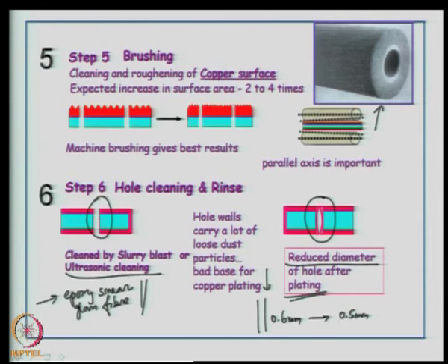So, what you will try to do is force its entry into the through wall, and as a result you will break the plated copper, which will result in an open.